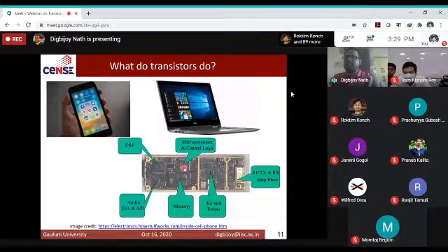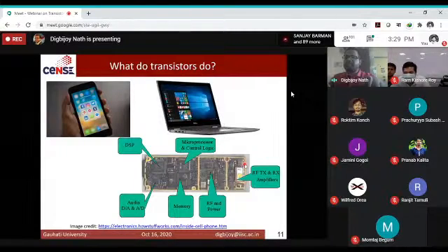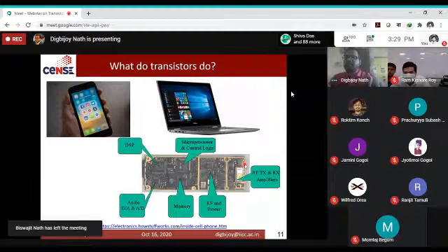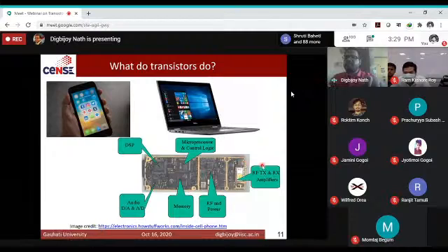A chip over here is the RF transmitter and receiver. The phone does not magically send you the picture or video. It has to convert the signals, the zeros and ones, into electromagnetic waves, probably around 1 gigahertz or 2 gigahertz, and send these waves through an antenna to the atmosphere, to the nearest base station. So the radio frequency transmitter and receiver is for that. It is typically made of complicated devices, transistors, but a little bit more advanced transistors. I'll talk about that later. And then there's a power handling module, there's memory.